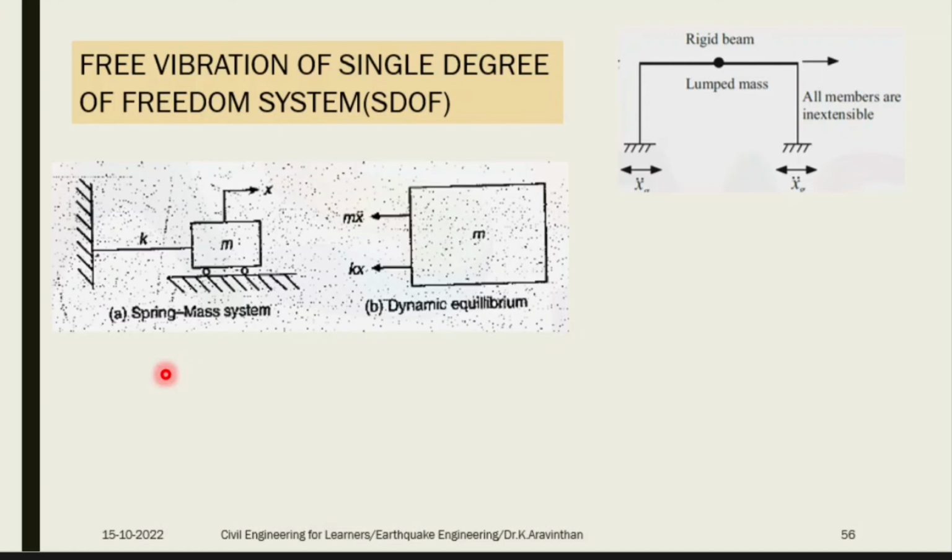Now what you are interested in is drawing the free body diagram. How to write the free body diagram? After removing all the external forces, only the mass will be there, and whatever it is connected to, you will indicate as a force. Now, if I am trying to pull this mass here, will this stiffness allow? No, it will not allow. Why? Because it is caught. You imagine that it is caught in a thread. This will not allow, hence K will be in the opposite direction.